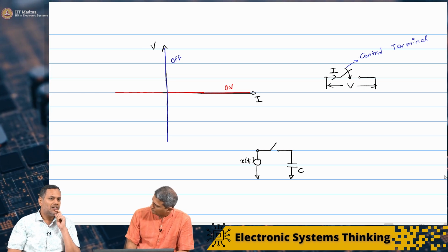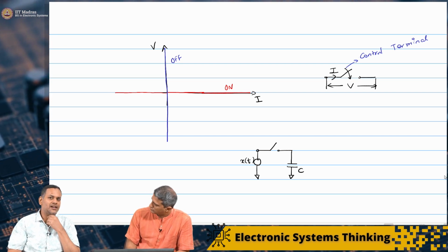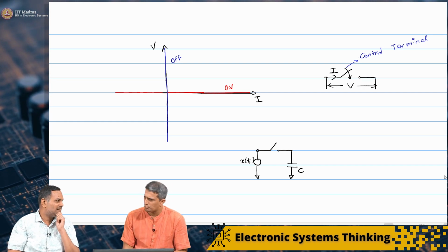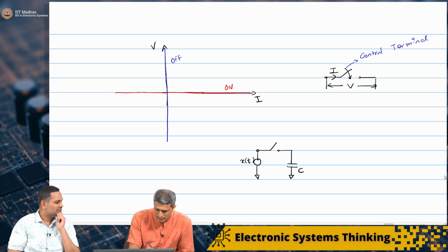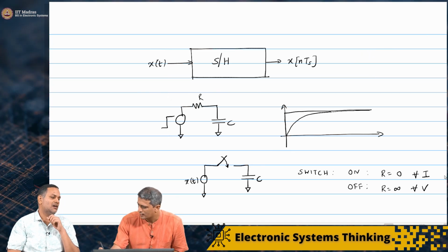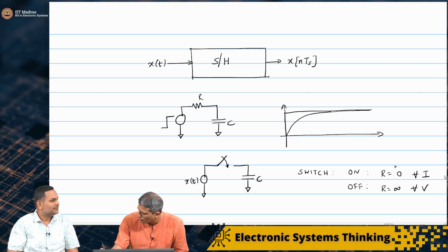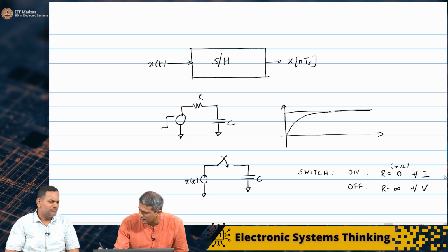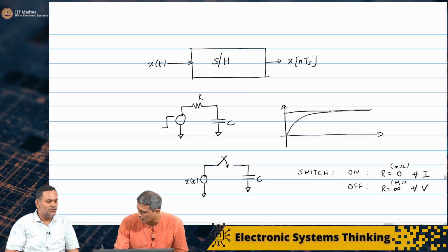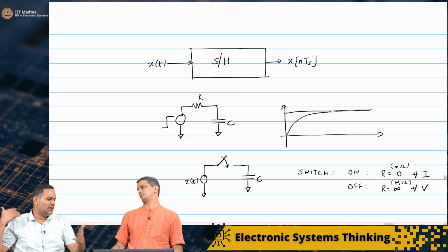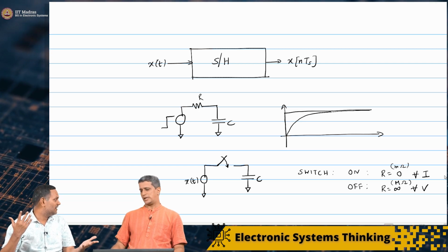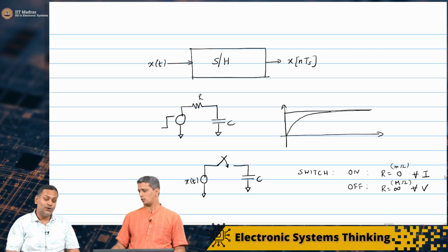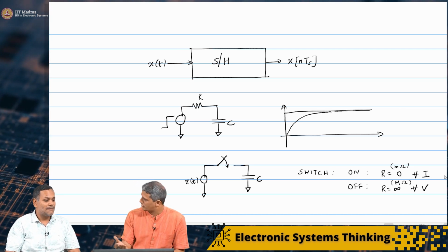In this specific case, if you are using an ideal switch, it does not matter. In reality, this assumption that we made will probably have maybe milli-ohms of resistance in the on state, and the off state might be in mega-ohms. So they are separated by maybe 6 decades, or even more, actually 9 decades, 9 orders of magnitude. So that's a good approximation of a real switch.